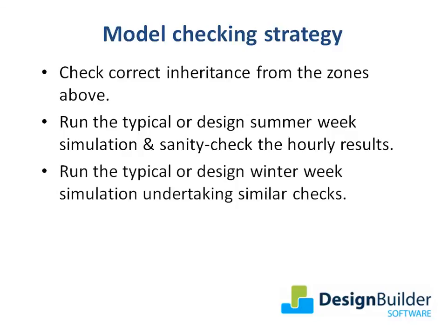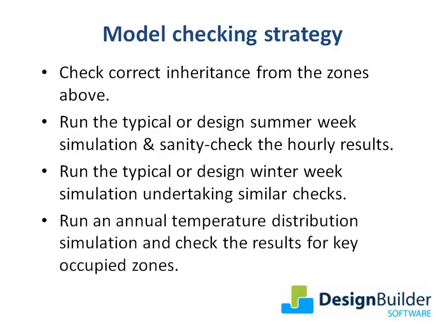Next, run the typical or design winter week simulation, undertaking similar checks. And finally, run an annual temperature distribution simulation, requesting distribution data and check the results for key occupied zones. Once you've completed these checks, you can be confident that your model is behaving as expected, and the results should not be compromised by any major data entry errors.